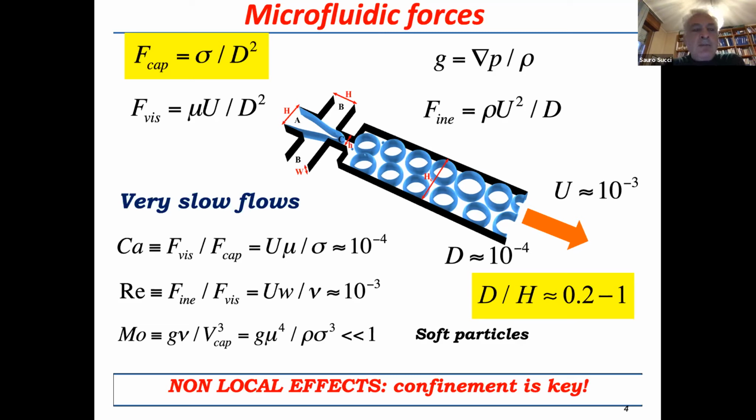So again, forget about all these dimensionless parameters. The numerical complexity is often driven by the fact that these droplets have a size which is fairly comparable to the micro device they are flowing within. Typically, you could think of a droplet around 100 micrometers or 200-300 micrometers, and the channel length, I don't know whether you can see my pointer, HC, is of the order of less than a millimeter.